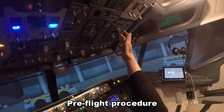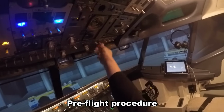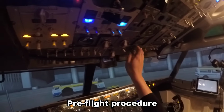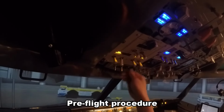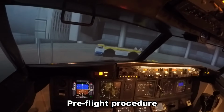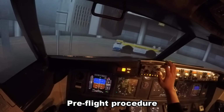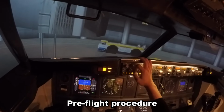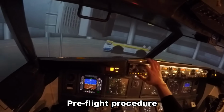Pressurization mode selector set to auto. Ring lights are off, anti-collision lights should be off, position is just steady, and we'll have the logos on. Our engine start switches should be set to off. We'll turn off all the external lights. We'll next program our EFIS, and the altimeter is 1009.